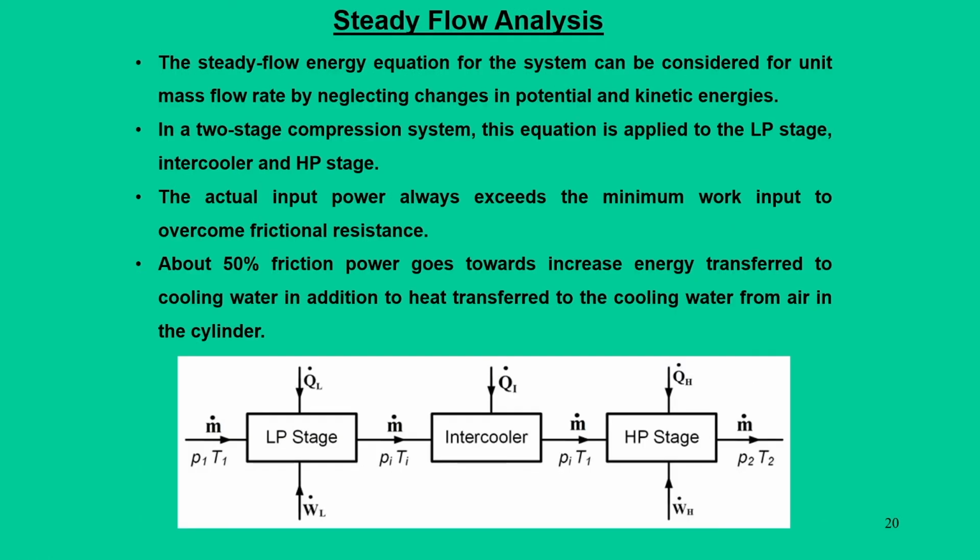Okay. The next part of our analysis is a steady flow analysis, which we are going to deal with for a 2-stage compression system. After dealing with multi-stage compression, let us see if we can do some kind of analysis. We have seen that the compressor is always integrated with thermal circuits to take out as much heat as possible, with the main intention of making this compression process resemble isothermal compression, to minimize the work.